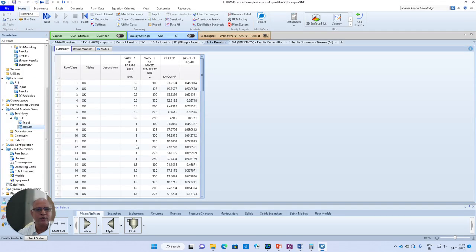when you increase the pressure, what will happen? The partial pressure will increase, right? The mole fractions, the amount of CHCl3 remains the same, but as you keep on increasing the pressure, the partial pressures will increase. If you increase it beyond a particular limit, there can be an adverse effect because of the adsorption term. There may be a maximum also. Anyway, this is how we will be able to see the effect of temperature and pressure on the conversion. So let me plot this behavior.